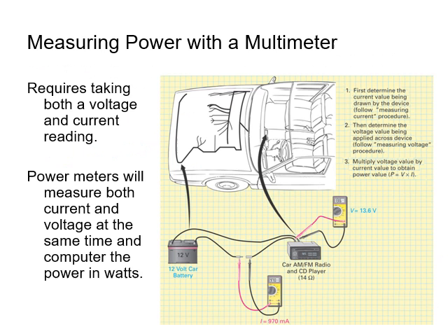All right, next. So next we talked about a multimeter to measure the power. It's going to be practically measuring two things. It's going to be measuring the voltage, and it's going to be measuring the current. And then inside the multimeter, it's programmed to do the math and multiply 13.6 volts times 970 milliamps to calculate the power in watts.